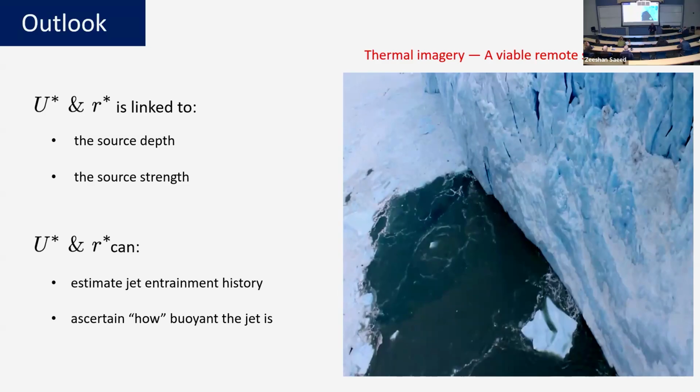The thermal camera doesn't really care about density. It cares about the temperature differences. So if I heat this part of the wood at a different temperature, it will show me that this is at a different temperature and this is at a different temperature, even though they might be at the same density. So it doesn't rely on density differences, just temperature differences.